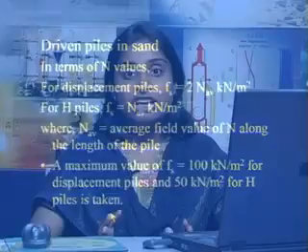Whenever you are finding out point bearing resistance or skin friction resistance, you have to keep a check that those particular values which you are calculating from an empirical formula should not exceed the limit which has been specified by different research workers from their experience and engineering judgment point of view.